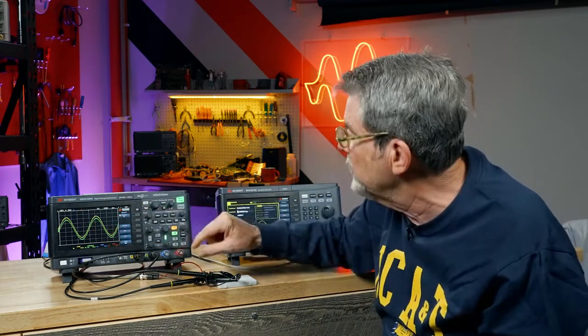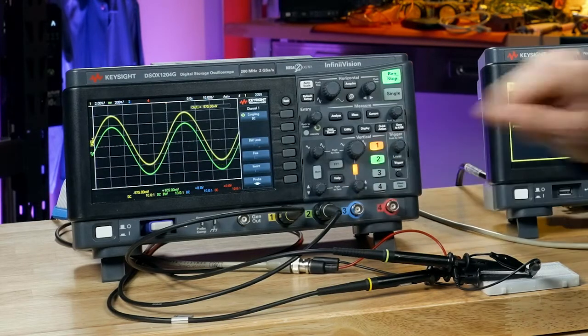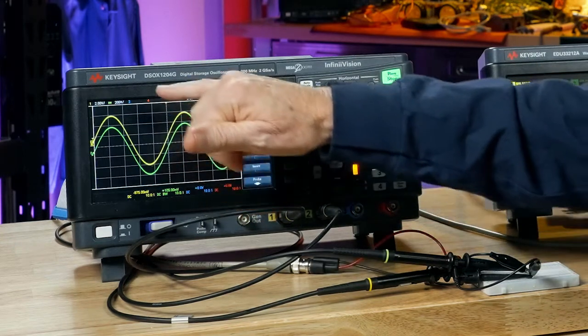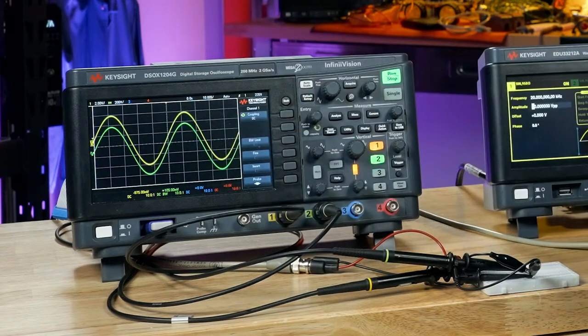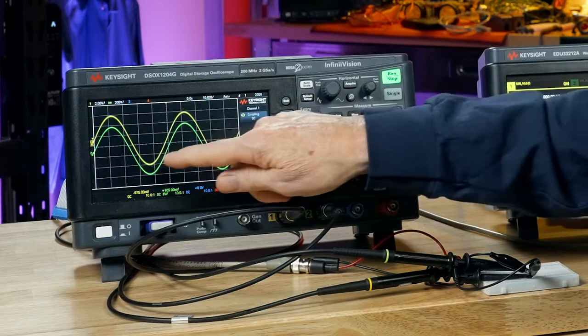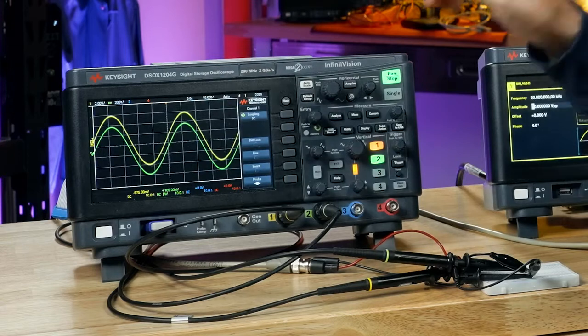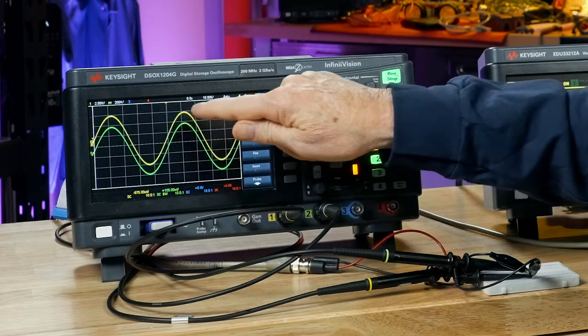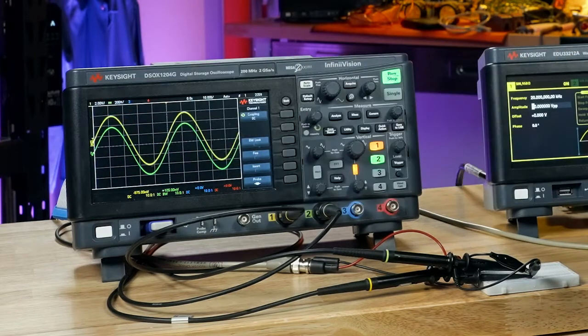And so let's see how big the channel 1 waveform is. I'm going to reposition it a little bit here, position it up here. There are divisions on screen. That's these white lines. The distance between the white lines is called a division. The yellow waveform, Vn, from top of R1 to ground: 1, 2, 3, 4, 5. It's about 5 divisions high, times 2 volts per division tells you that it's about 10 volts peak to peak. That's exactly what we expect.